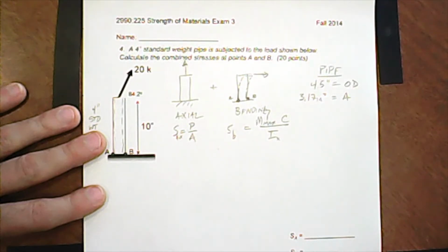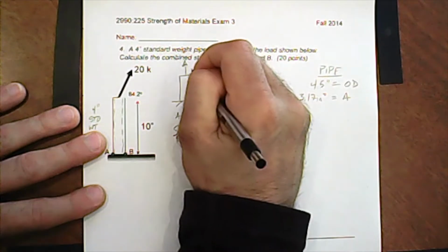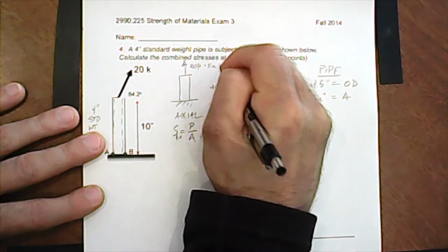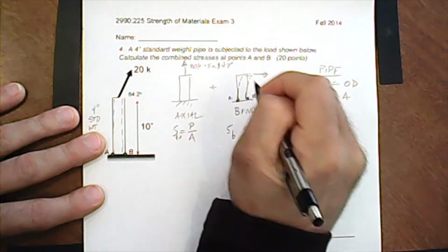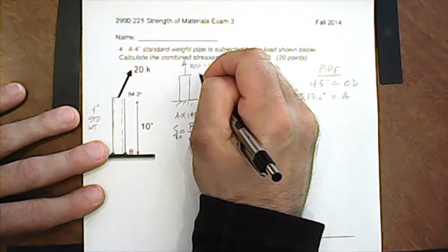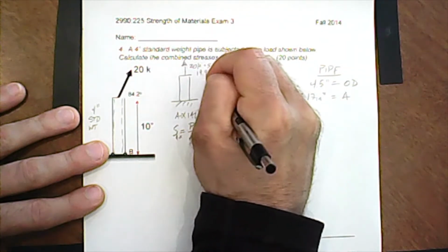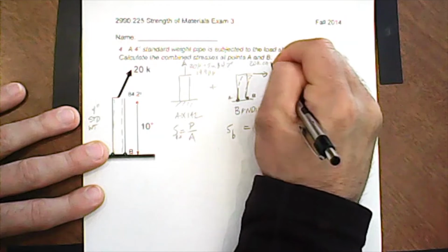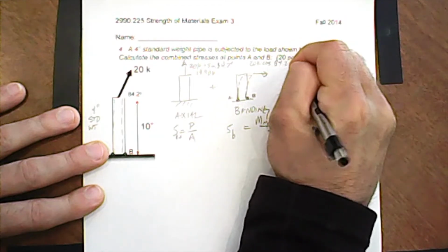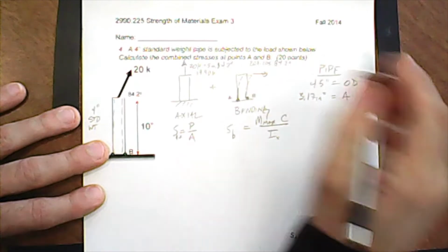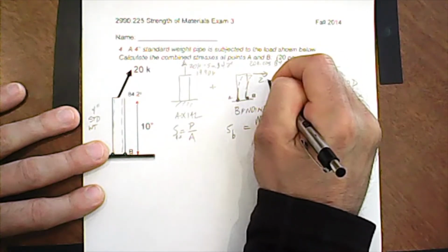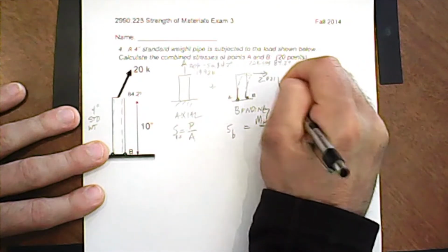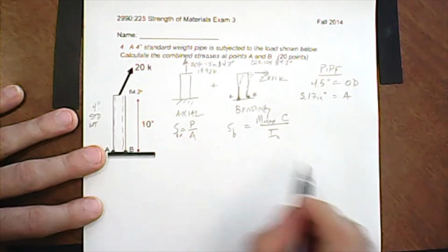Okay, and it turns out that this vertical is going to be 20 kips times the sine of 84.2 degrees, and that equals 19.90 kips. That's our vertical load. Our horizontal load is going to be 20 kips times the cosine of 84.2 degrees, and that should be much smaller, and it is. It's 2.02. In fact, let's do the same with 4 sig figs. So 2.021 kips, right? That gets us where we need to go.